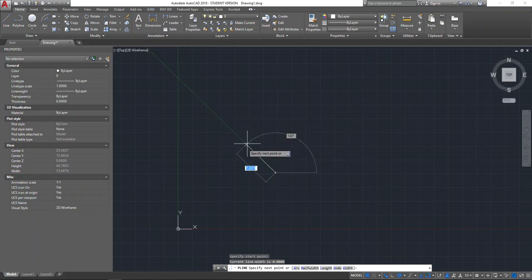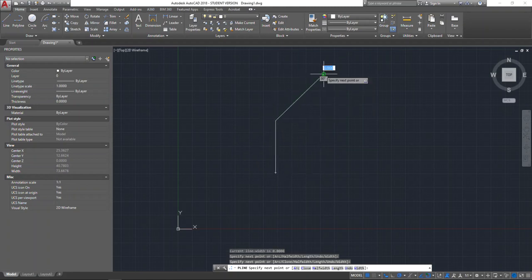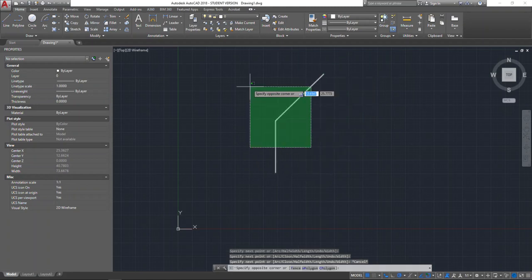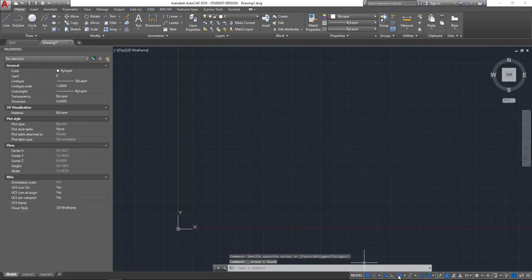For those of you using axonometric drawing, this is going to be a really useful tool because you can go vertically, then go off in that direction, and create axonometric drawings really easily. For those of you using isometric drawing, you can do 30, 60, 90. So if we draw a polyline now, you can see we can snap in my 60 or in my 30.